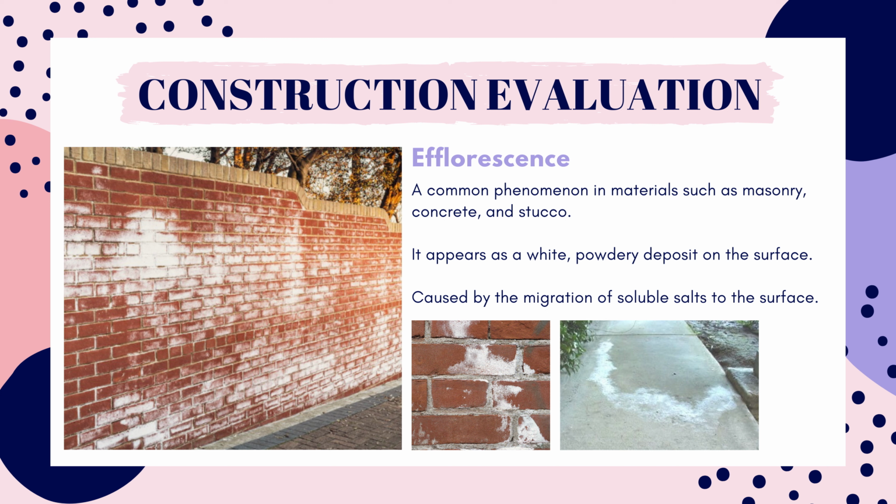Well, not necessarily. While it's not the most beautiful thing to look at, it can indicate underlying issues with the construction of the wall or the drainage or waterproofing of the wall, so it's something to investigate further.